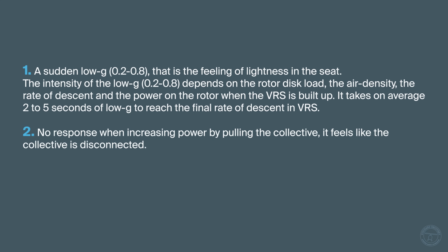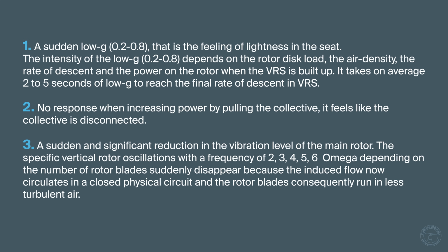Number 2. No response when increasing power by pulling the collective. It feels like the collective is disconnected. Number 3. A sudden and significant reduction in the vibration level of the main rotor.